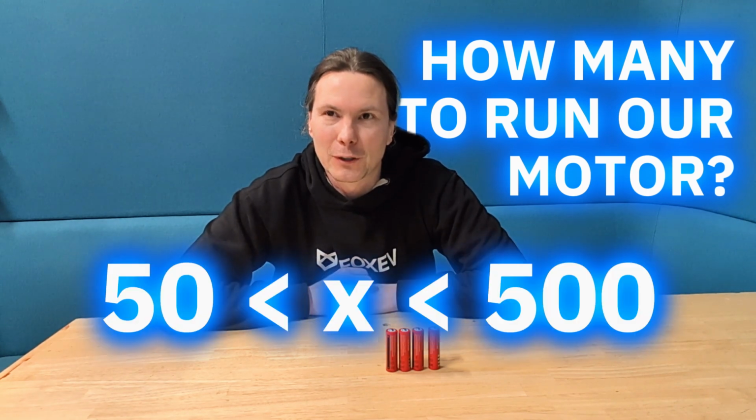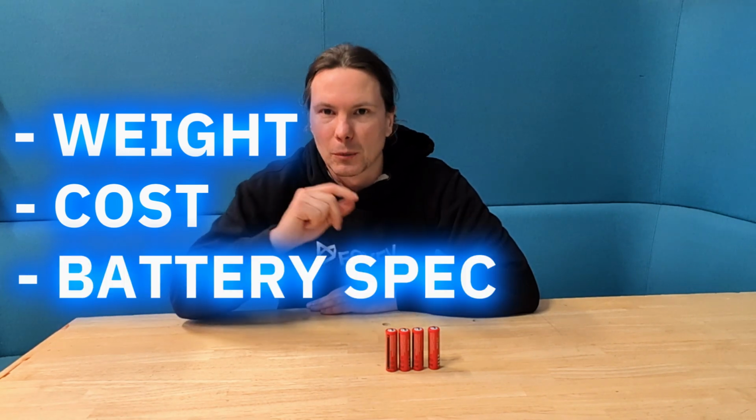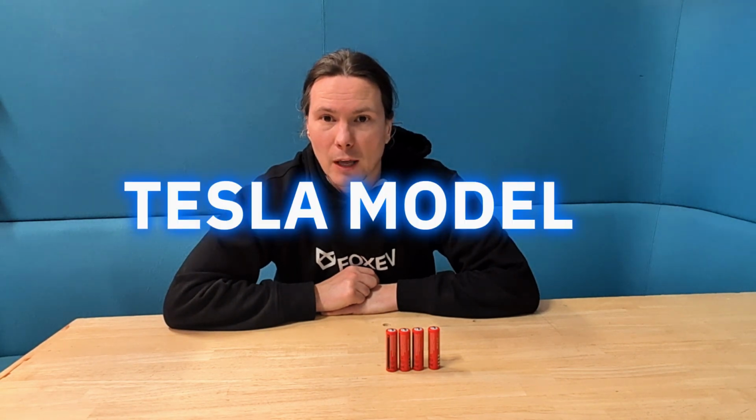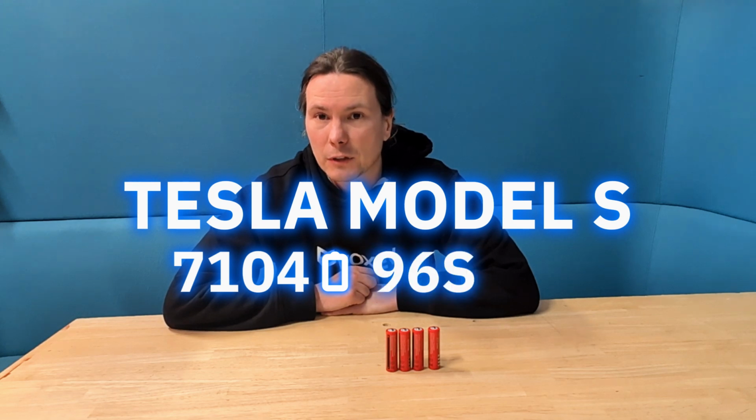So the answer of the calculation is between 50 and 500 batteries in parallel to run our electric motor. And the exact result depends on the weight, the cost, and the battery spec. So the cells that we saw in the data sheet, maybe they're not quite right. As an extra data point, I've given you the Tesla Model S, which has got 7,104 cells and 74 of those in parallel. But the approach that I've shown you is exactly what you do.